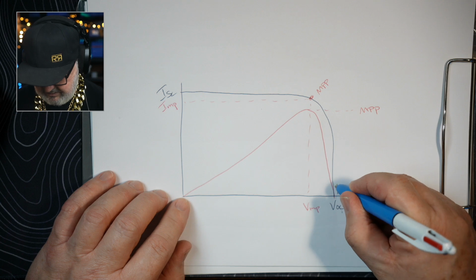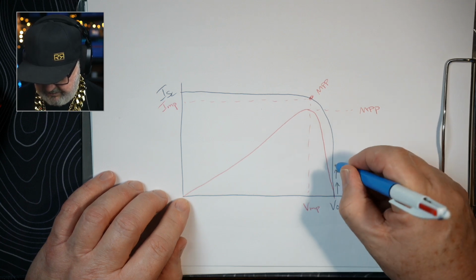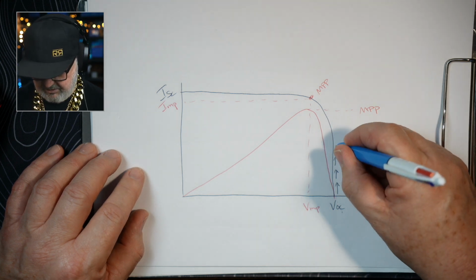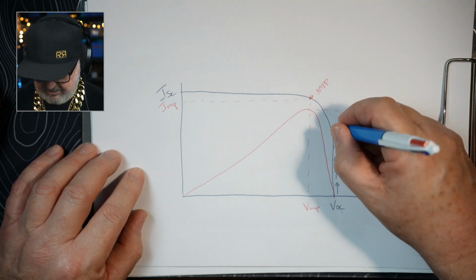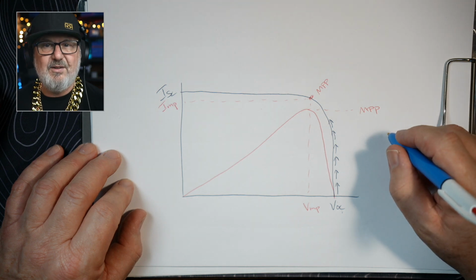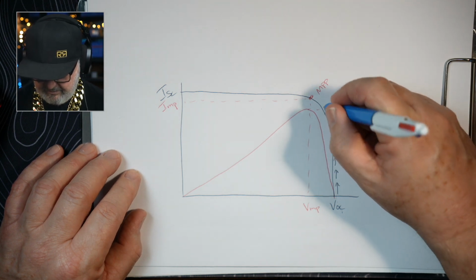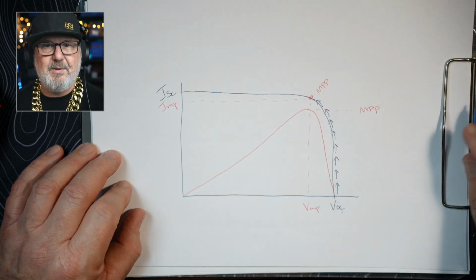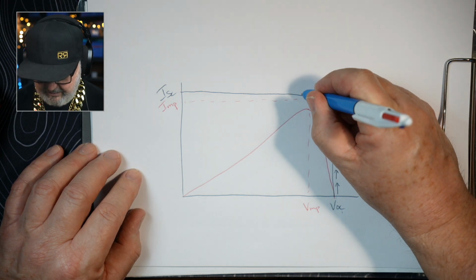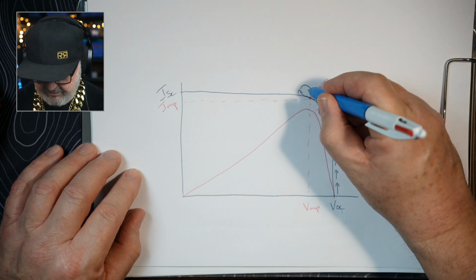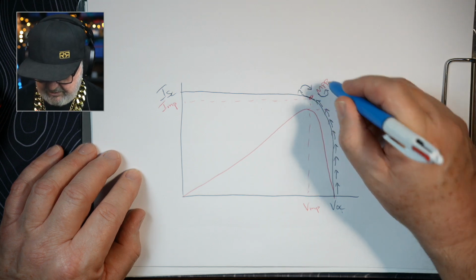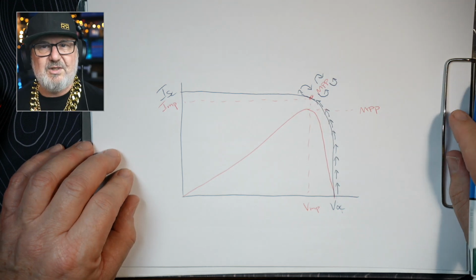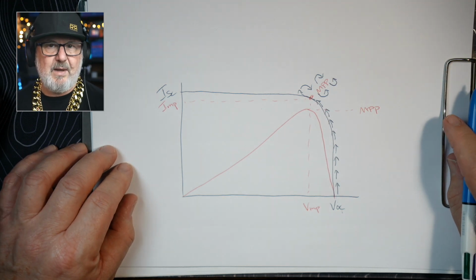So it can see voltage coming off the PV array. So what it does is it starts to draw current, and as it starts to draw current into the charger, the voltage starts to drop and the current starts to increase. So it's tracking along this curve, the IV curve. It's also known as a load line. And at some point, it gets to the maximum power point, but it doesn't know it's there until it's gone too far. It's gone too far, and so it turns around and comes back. So actually what it does all day long is tracking the point at which the product of voltage and current gives it the most power.